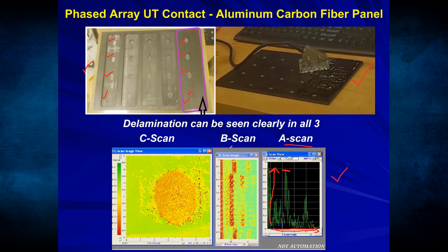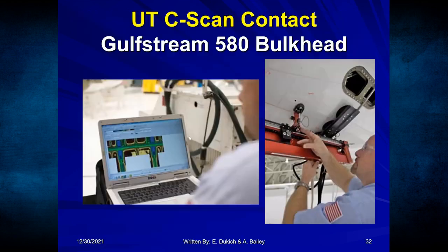But that's the only information you have, so you've got to be very skilled to compare that to the part. Now the B-scan application here shows you a cross-sectional view or a side view. So it shows you where approximately the flaw is if you had the component on its side, kind of like that's shown right here. But the C-scan shows you a top view. It's also called a plan view. So if I flipped it, it actually shows you the top side view, like you're looking from the top down. So if I flip this over, which is what's shown here over to the right, you can find the flaws without even seeing these layers here. And that's the purpose of NDT, to find the flaws that you cannot see with your naked eye.